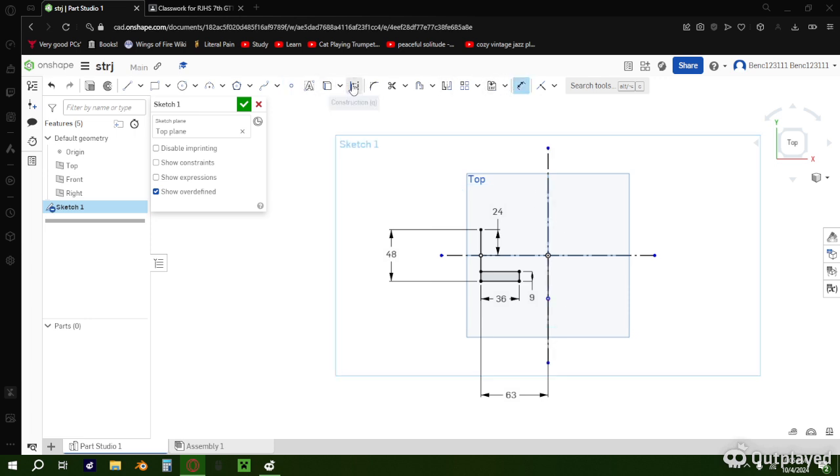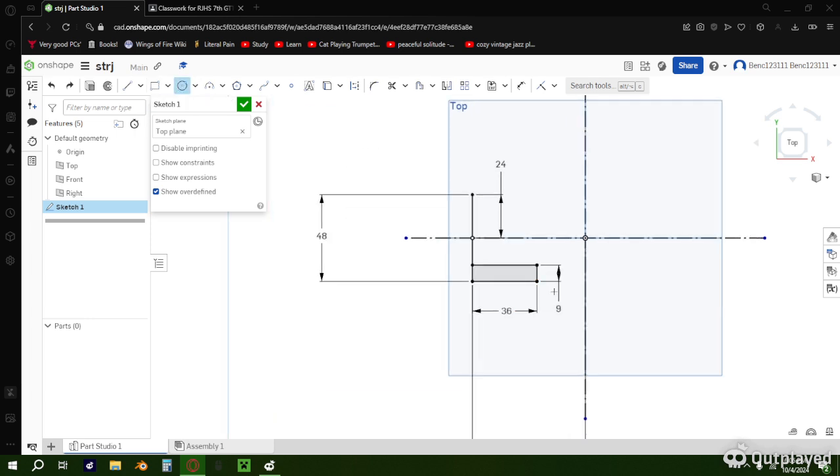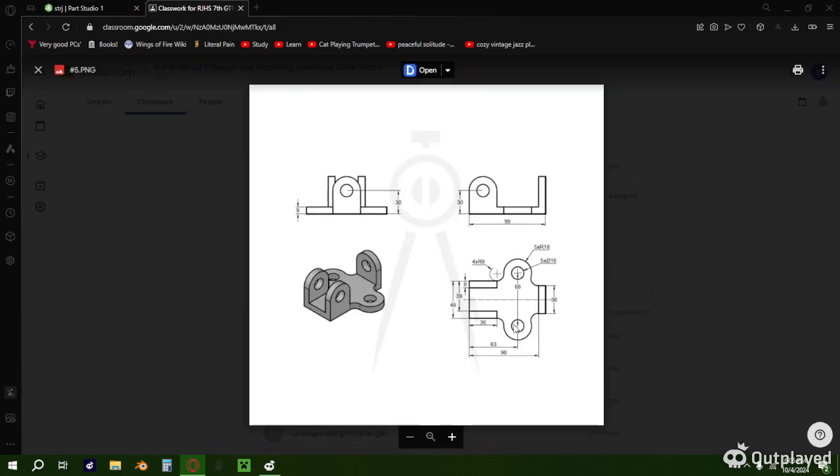Or rather, actually a quicker way of doing this would be, instead of adding a point, you would just take a center point circle and just put it down anywhere. Also, the diameter of it is 16. So then from there, we need to take the dimension from the center point up there to the origin. That is 34, I believe. Let me see. Yeah, 34. So then we already have it like this. We have these circles down.